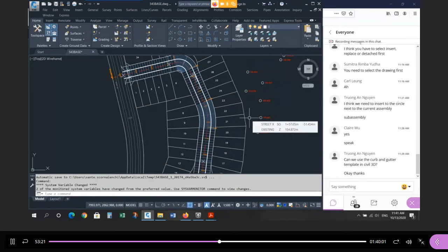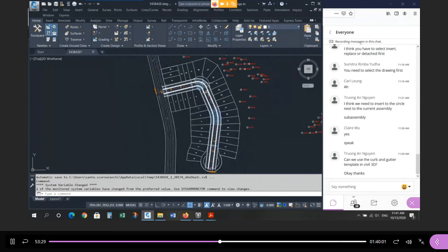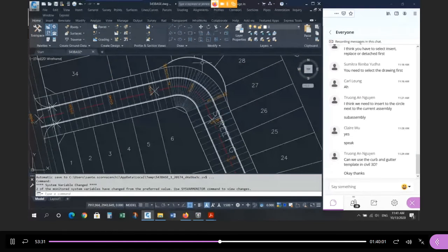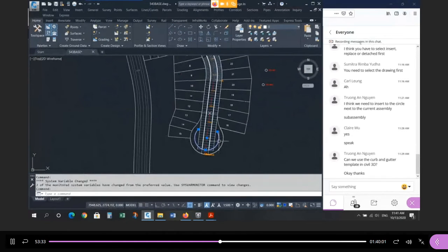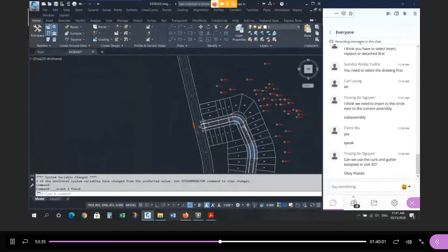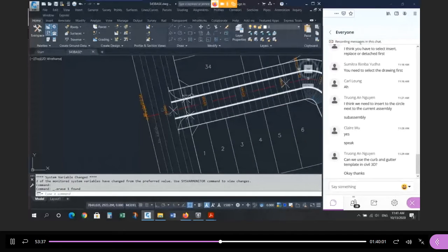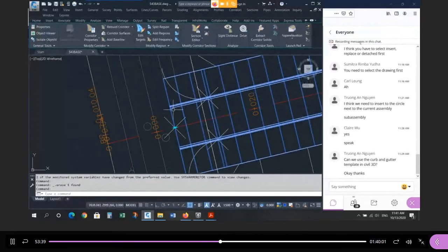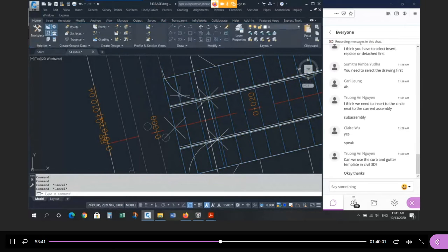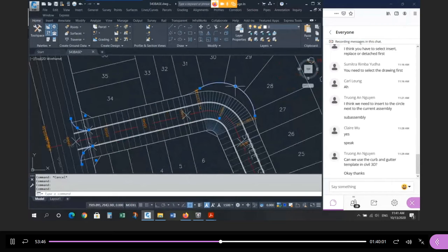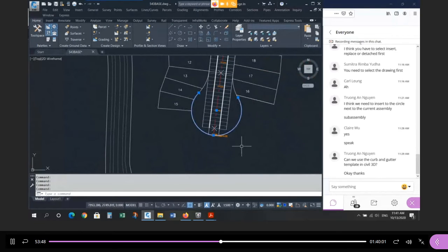Okay, there's 3 things not quite perfect about this yet. Okay, we're going to get to that. It does not represent the elbow correctly, and it does not represent the cul-de-sac correctly. Even the intersection, right, doesn't work too well. The road looks like it wants to go all the way to here, when really it should stop at the curve and go around, right? It should really respect this alignment. The street line should be way out here.